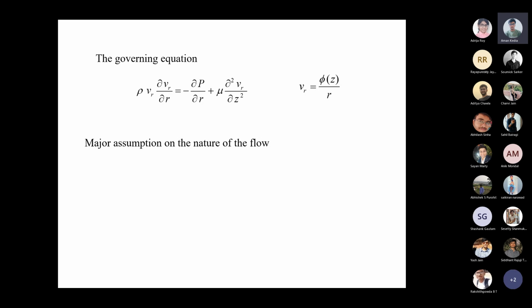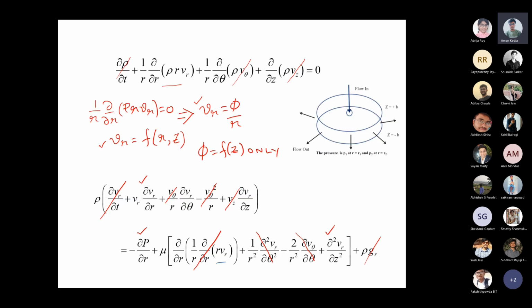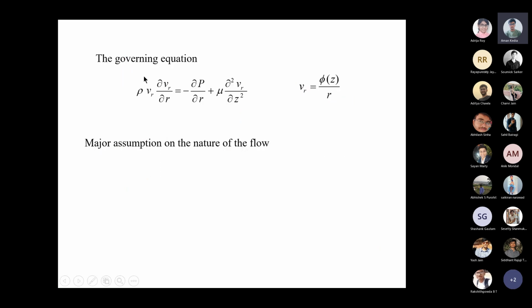Whenever velocity appears apart from a velocity gradient, most likely it's going to be a convective transport. If you look back at the previous one, this term has come from this, and we know that the left hand side of the Navier-Stokes equation is essentially convective momentum. So this is the first time that we are dealing with a term whose nature is convective. This is pressure. This is a flow created due to the pressure gradient, and the obvious appearance of mu ensures that what we are dealing with is a viscous transport term.